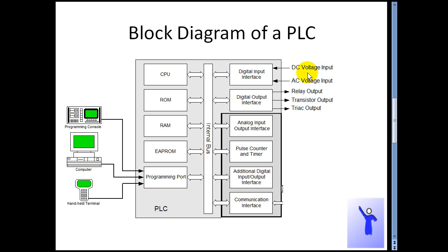They accept industrial voltage levels, they are mostly noise proof, and they support connecting industrial devices like bulbs, motors, contacts, relays, switching devices, etc. They can be easily connected. All industrial devices can be connected to a PLC either as input or as output, as the case may be. So this input output system is very robust. This industrial customization of the input output system of the PLC is what makes a PLC very special.